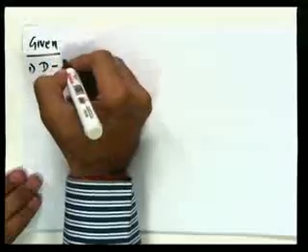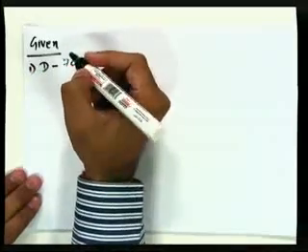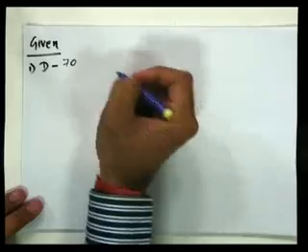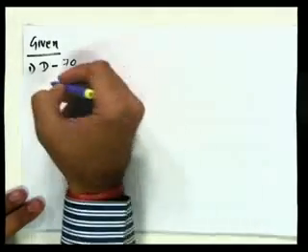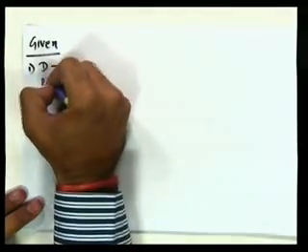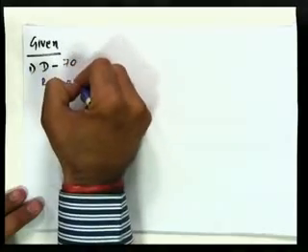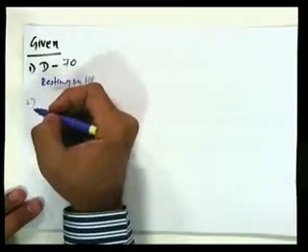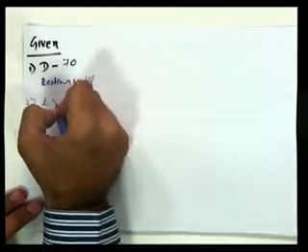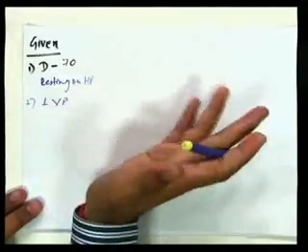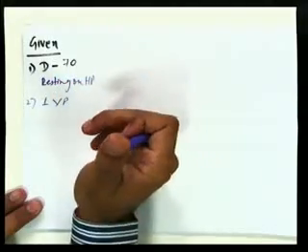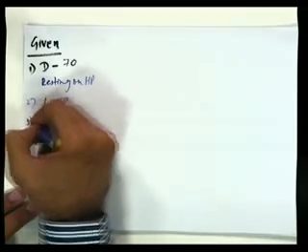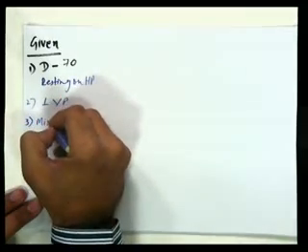The diameter of the plate is 70 mm, and it is resting on HP. The second thing that is given to us is the plate is perpendicular to VP. That is obvious because it is lying on HP, so it will be perpendicular to VP and inclined to HP in such a way that the ellipse which is formed has a minor axis length given